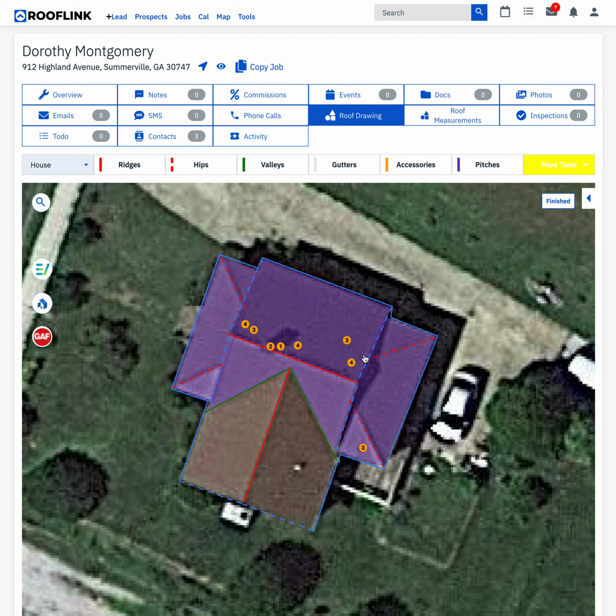So you would take and click here, and you're just going to run that length that's sloped, and then you're going to run this length that's sloped, and so that's allowing for step flashing there. We're going to do the same thing here to here, and here to here.